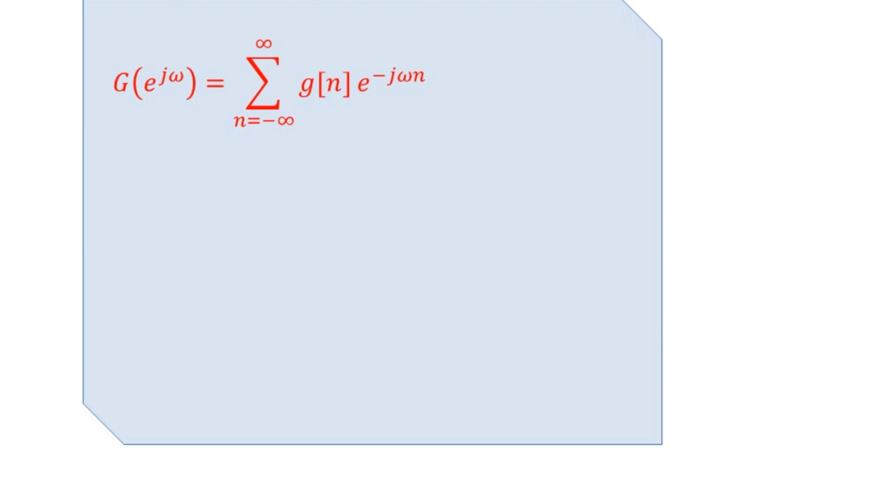We can have another notation as gamma of n, that is equal to the product of the initial infinite length sequence g of n with the window signal here for a finite length. So the spectral characteristics of the windowed finite length sequence can be obtained by again performing the Fourier transformation. The same mathematical formulation as we have here, the equivalent form we can have for such a finite length sequence here, making the changes to the limits of this particular summation.